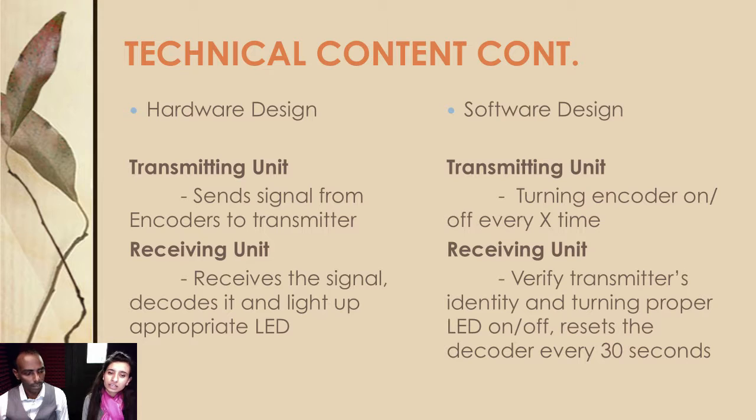For the hardware design of our device, the transmitting unit sends a signal from the encoders to the transmitter, and the receiving unit receives that signal, decodes it, and lights up the appropriate LED. For the software design of our device, transmitting unit turns on and off the encoder for every X time. Receiving unit, however, verifies the transmitter's identity, turns on the proper LEDs, and resets the decoder every 30 seconds.